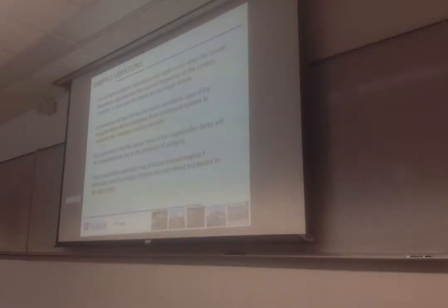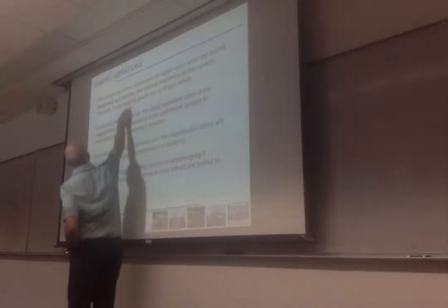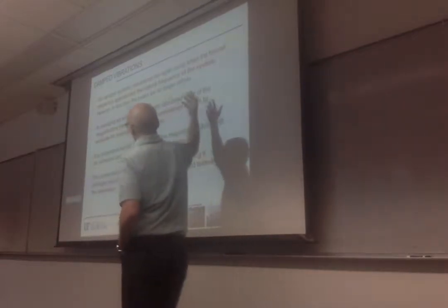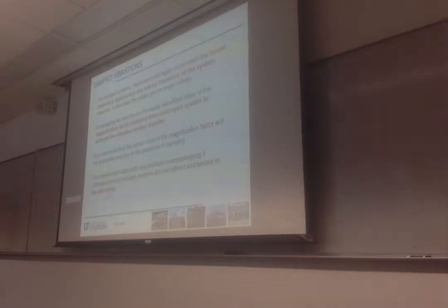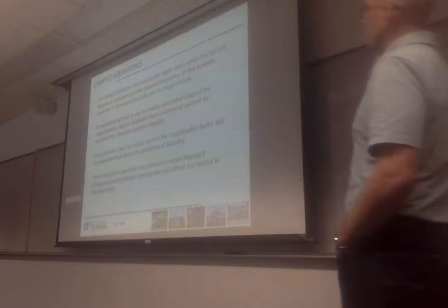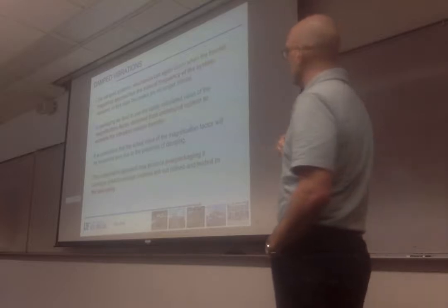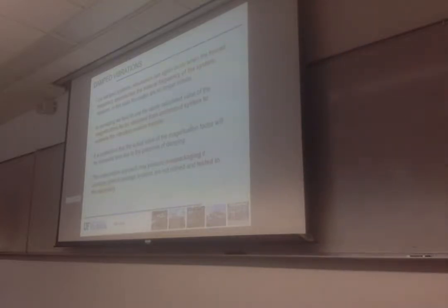And again, an important distinction, it's not in orange, but it should be: the peaks are no longer infinite. Obviously, in the real world we're not dealing with something that goes to infinity, so it's going to be finite. In packaging, we also tend to use the easily calculated value of the magnification factor we used before to estimate the vibration motion transfer.